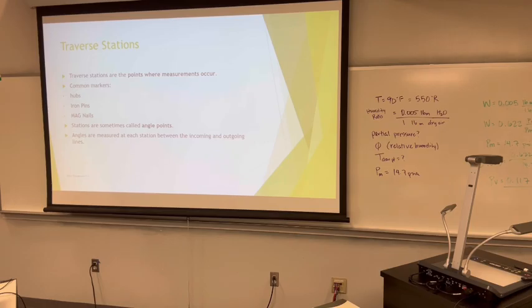For those of you that are going to work at survey companies as well, your company is probably going to have their own standards as far as what they require you to use for control. I'd be willing to bet you a dollar most, not all, would recommend wanting to see iron pins for control points on a traverse, especially on a job site. You may even have to dig holes and mix concrete and set a concrete monument too, depending on the project.